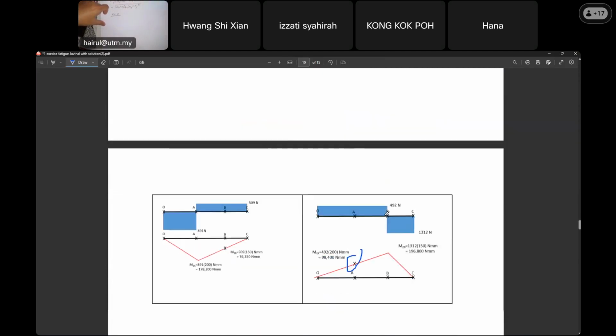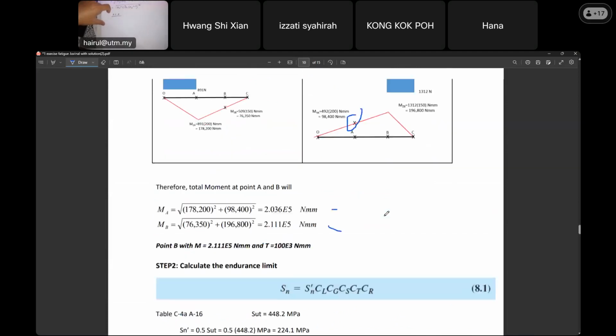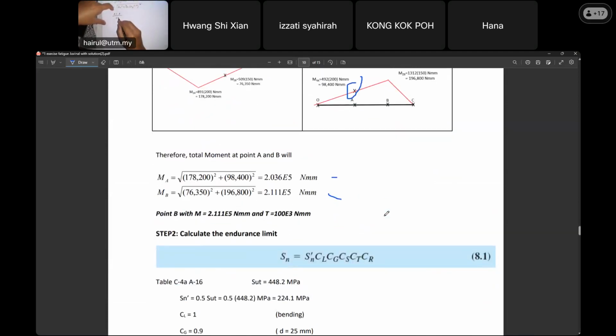All right. Now at B, the critical bending moment is at B. So the bending stress, sigma bending, is 32 M over pi d cubed. This is a shortcut for a solid round shaft. Actually it is MC over I, which gives 32 M over pi d cubed. This is bending stress, right? With the moment at B. Class, are you watching or not? What is the moment at B?